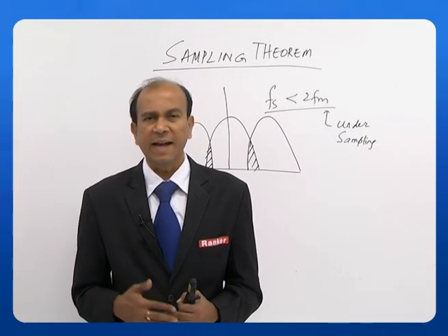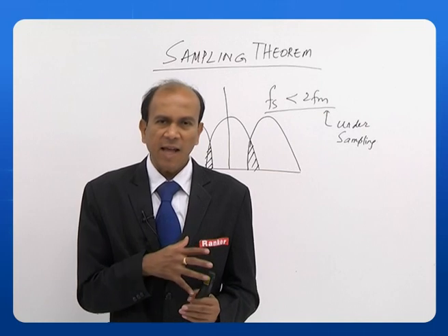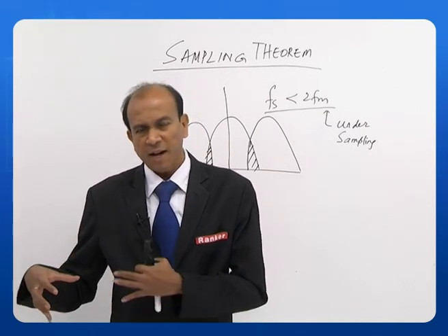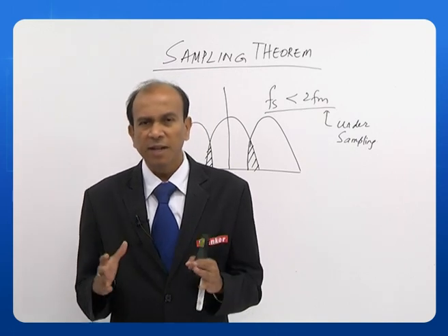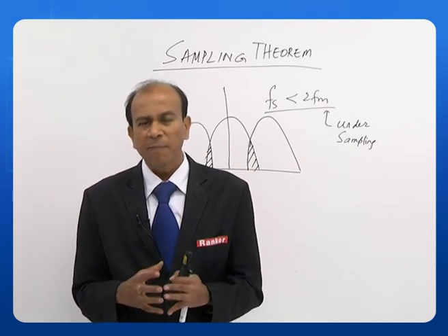These are called anti-aliasing. So, to avoid aliasing, use a pre-filter and increase the sampling rate to Fs greater than 2FM, then you will get a signal which is free from aliasing.